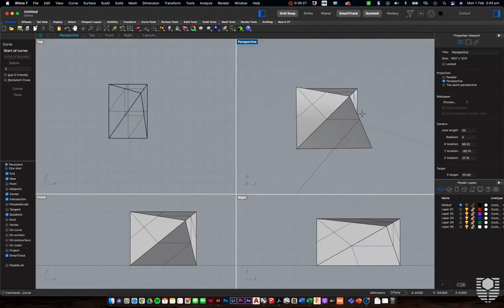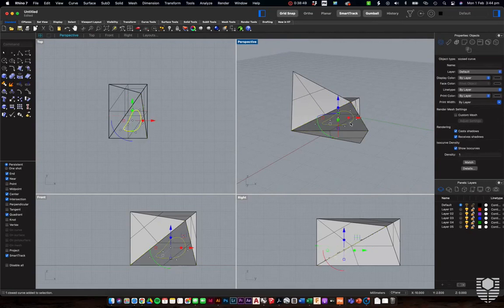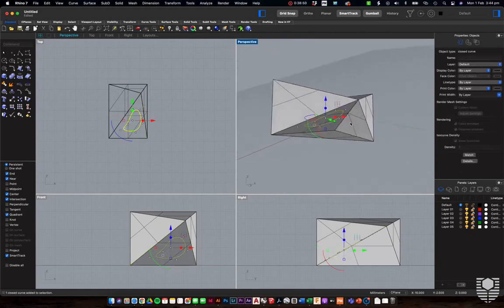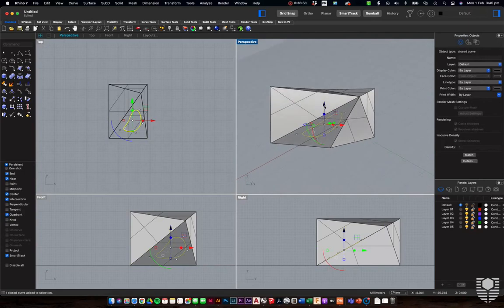So if again I go up to my freeform curve, I can now create a curve on top of that face without any worries of it going somewhere else. Now, if I then try to move that curve, I can see my gumball is actually going in a different direction at the moment. That's because it's still conforming back to the world view, and that might be okay for you, but it also might be causing some dramas, because if I wanted to pull this curve off perpendicularly to the plane that it's on, the gumball isn't currently going in that direction.